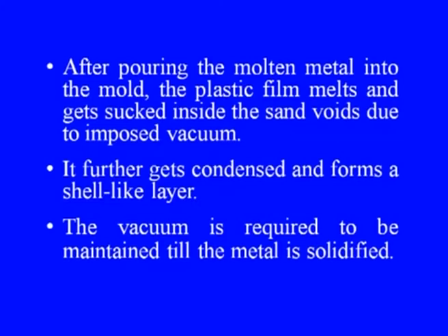The vacuum is required to be maintained till the metal is solidified. Then it is released, allowing the sand to drop away, thereby leaving behind the casting with a smooth surface. The process does not require shaking out matters and equipment to remove the casting out, and the sand can be reused after cooling without any treatment.